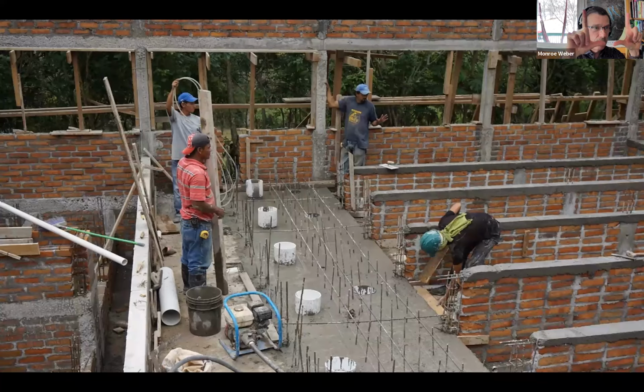That water level, of course, is the exact same level on both ends of the U of the hose, no matter where you drag it on your construction site. And so you can use that to mark a level over a relatively long distance. If that didn't make any sense, I'm sure if you look up water level on YouTube, there'll be somebody that will show you a nice image of that.